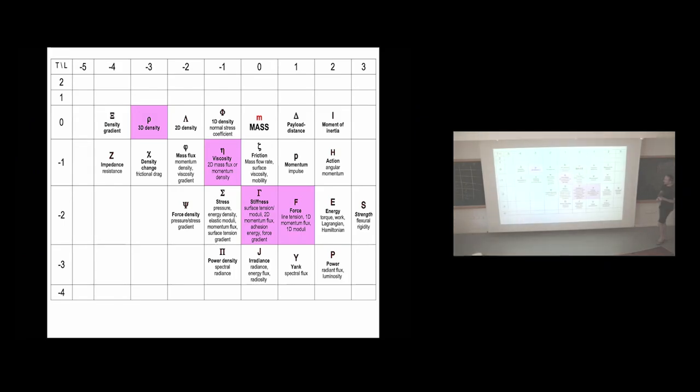And last time we had a surface tension, and we had a viscosity, and we had a density. And what we saw was that if you combine surface tension and density, what you get is a 2/3 power law. This was the first thing that we saw. Then if you combine surface tension and viscosity, what you get is a linear regime. And if you combine the three of them, you get the point of intersection.